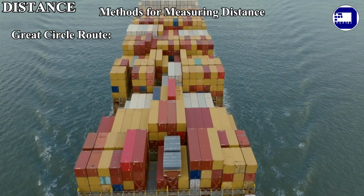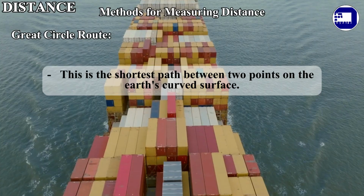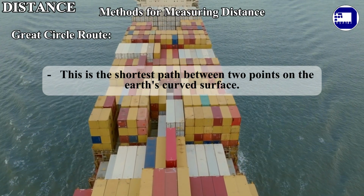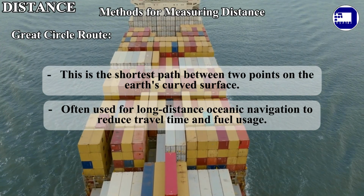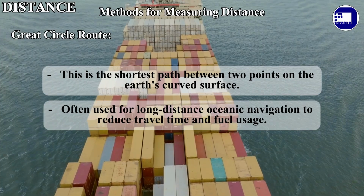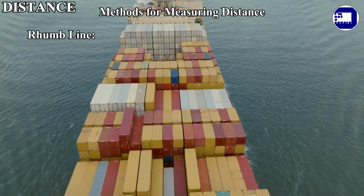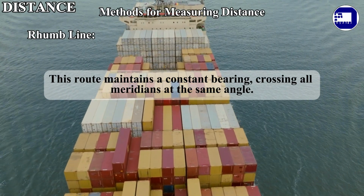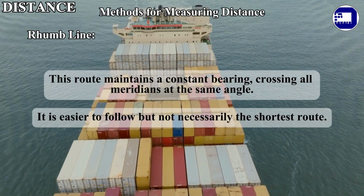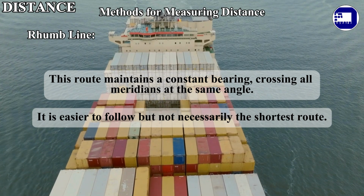Great Circle Route. This is the shortest path between 2 points on the Earth's curved surface. Often used for long-distance oceanic navigation to reduce travel time and fuel usage. Rhumb Line. This route maintains a constant bearing, crossing all meridians at the same angle. It is easier to follow, but not necessarily the shortest route.